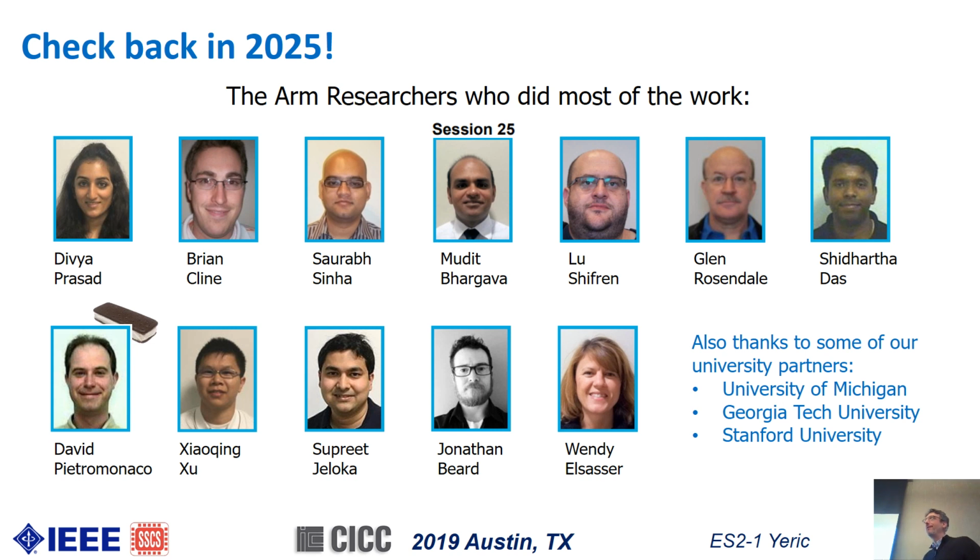So it might be that it's very good for certain applications, maybe in memory where it's slower, but there's evidently a lot of papers that are coming out this year that are looking at the frequency response of NCFET. I think VLSI's got a couple coming up in June. So we probably will know more this year, but for right now I just haven't seen a compelling write-up saying this is for real and it can compete with CMOS at high frequency.